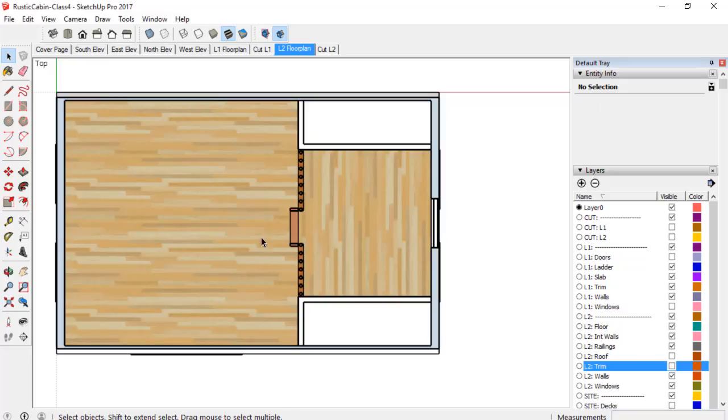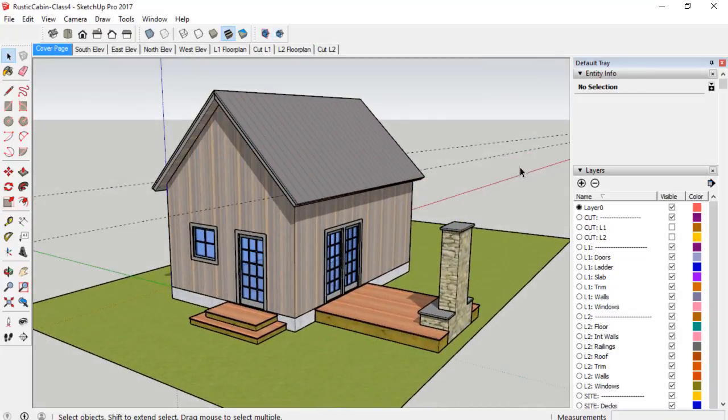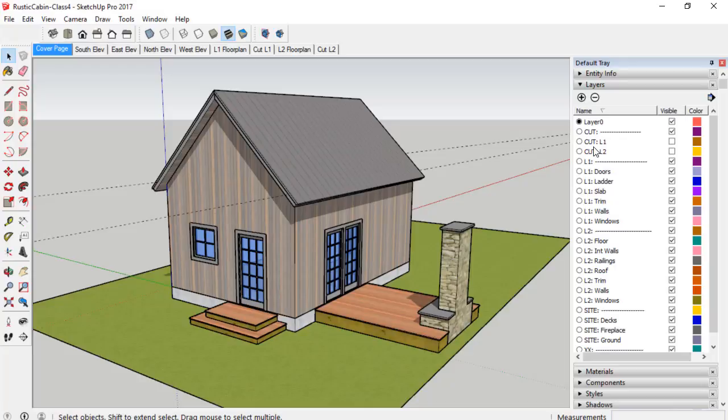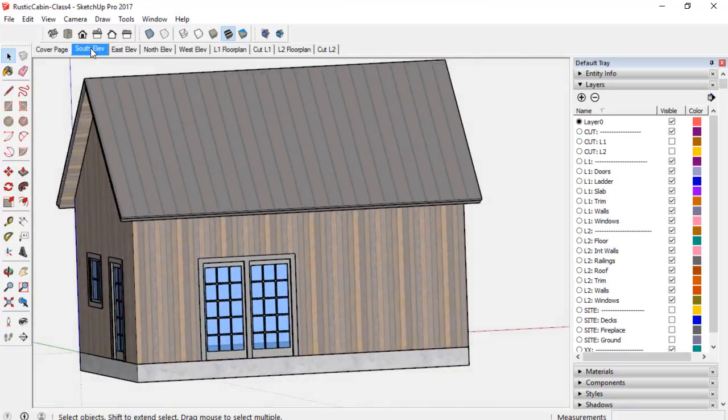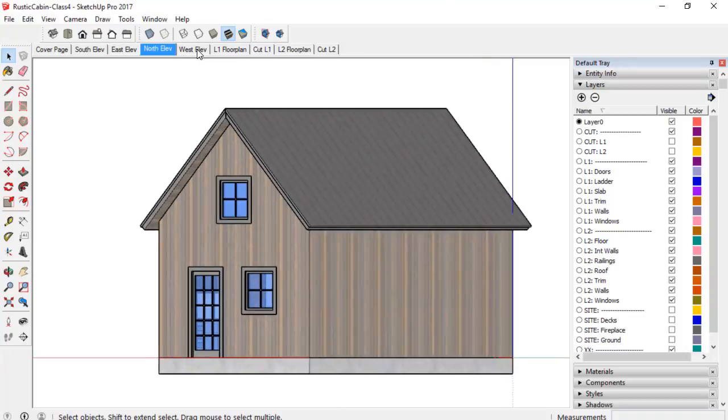And I'm going to go back into SketchUp. And let's look at our cover page, and there it is. We see those dotted lines. So let's see what's going on here. I assume that that is a section cut that we're seeing. But let me erase my guidelines. Maybe it's that simple. Oh, it was. Great. Okay, so I hid my guidelines, and I now will update and check the other scenes. They all look clean.